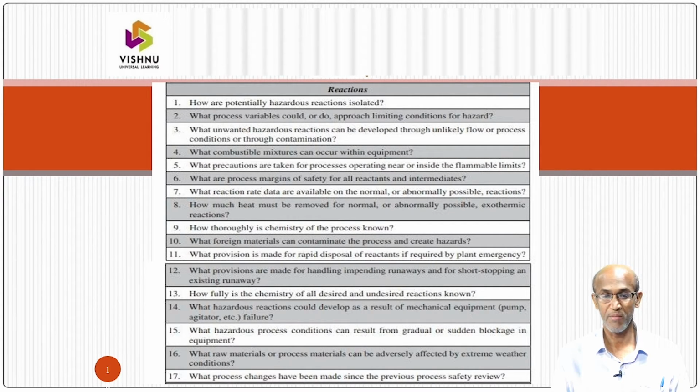What process variables could or do approach limiting conditions for a hazard? What unwanted hazardous reactions can be developed through unlikely flow or process conditions or through contamination? What combustion mixtures can occur within equipment?